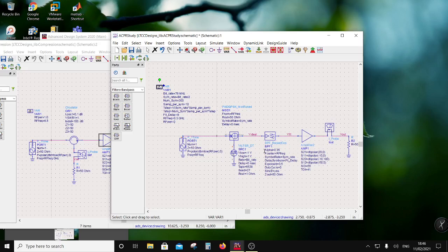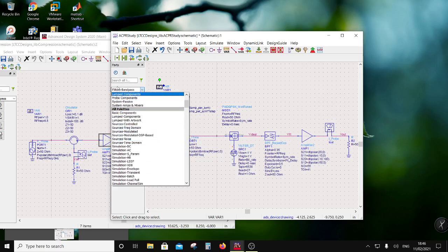So it is going to compress at 30 dBm, right? That's what we figured out. So we have to put in 10 to get the 1 dB compression point, right? Now I am going to do an envelope simulation. So where is this envelope simulation used?